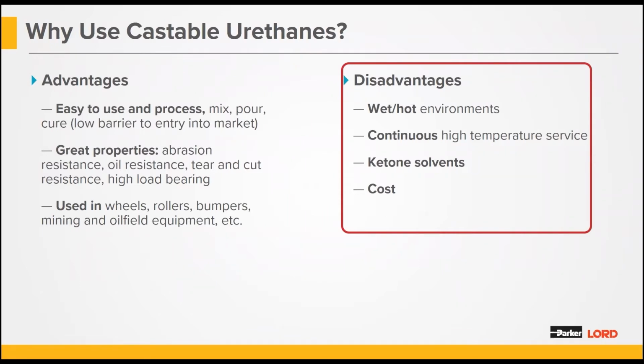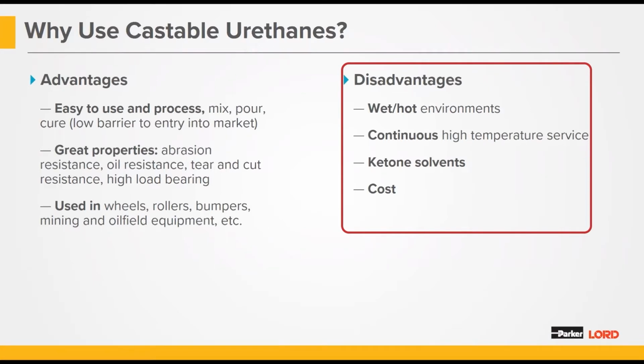Now, they do have some disadvantages. They don't perform particularly well in wet, hot environments, and in continuous high temperature service at 121 degrees C and above, they tend to degrade. They also tend to swell in ketone solvents, and they're pretty expensive.